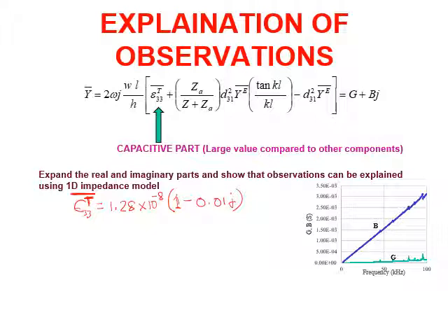Similarly, the other parameter is d31. This is 165 into 10 to the power minus 12 meter per volt. And you recall the unit of electric permittivity, that is farad per meter. Then we have the Young's modulus, Y E, with bar at the top.